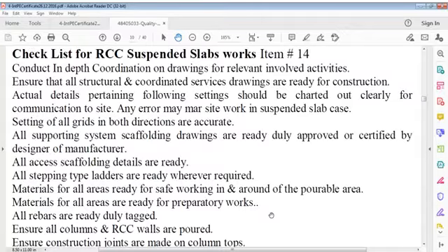You have to coordinate every service with structure. We have to think architecturally as well while doing services. When you enter some room, which is the best location where you can comfortably put the switch on, or do you have to put that outside the room because the room is a wet area? It's not recommended to put electrical services in a wet area or at a remote corner.